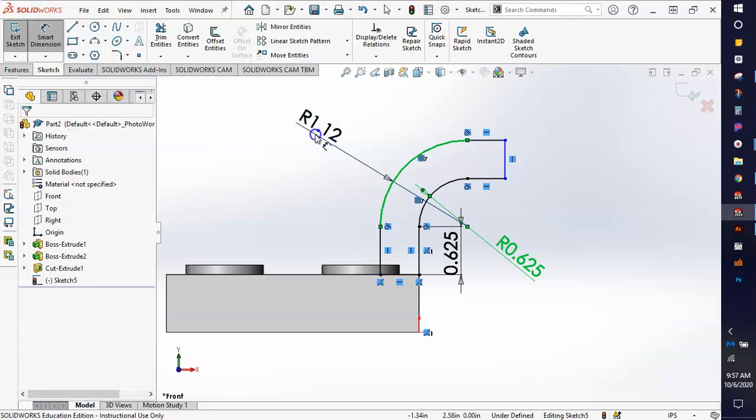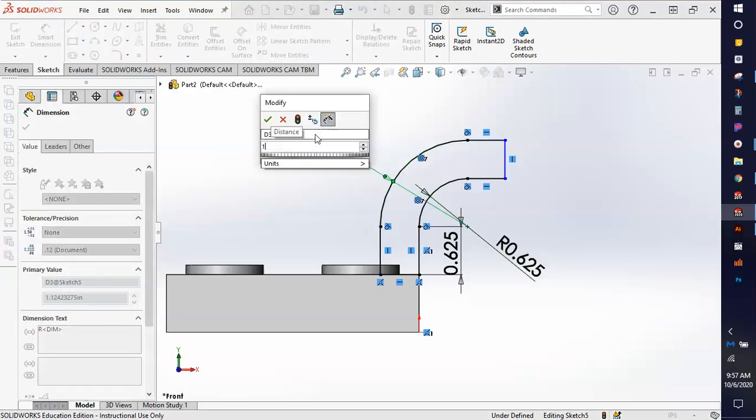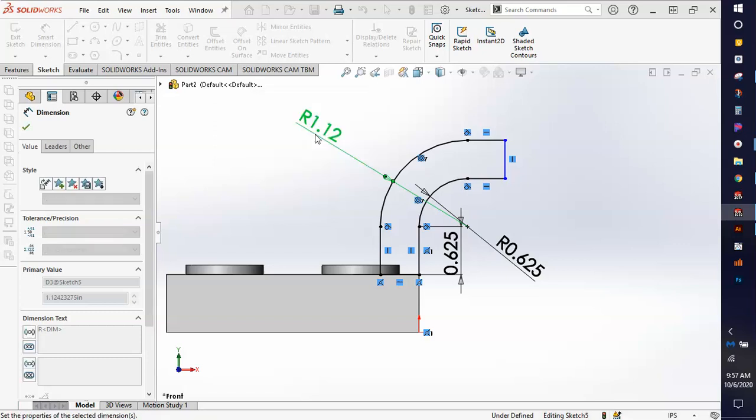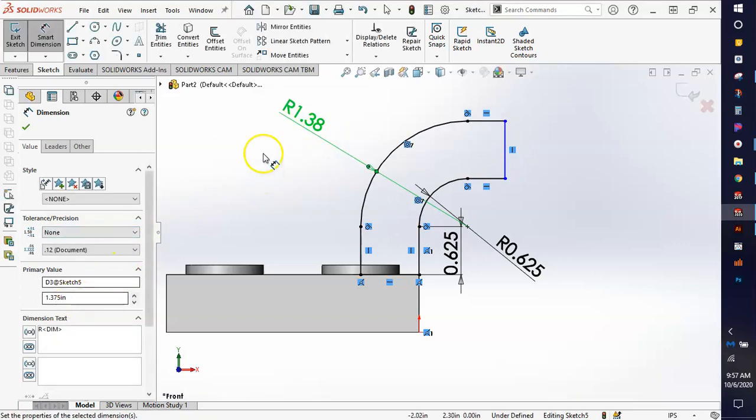It doesn't just simply spell it out. And this is 1 3/8. So 1 space 3/8. Okay, and it's not 1.38, it's actually 1.375. Okay, 375. Now you see how all this is fully defined because they share the same center point. So all of this stuff is locked in.